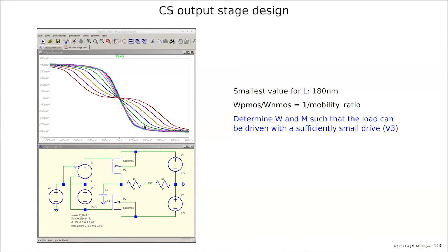The game has really changed, but let's say later on we can take higher quiescent current. So this is a function of the quiescent current and not a function of the width, of course. This is after I have selected the width. So for the PMOS, it ended up with 40 micron and 10, and for the NMOS, 40 micron and 3. So this is a factor of 3.3 instead of 4.5, but it looks quite symmetrical to me, and optimization can always be done later.